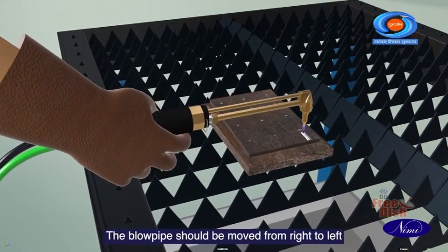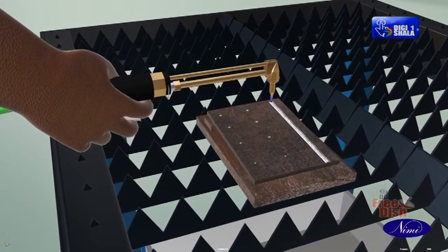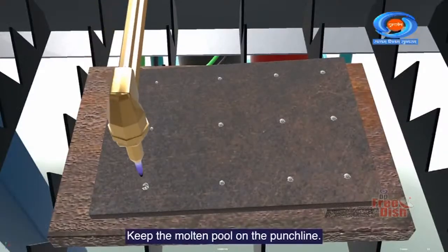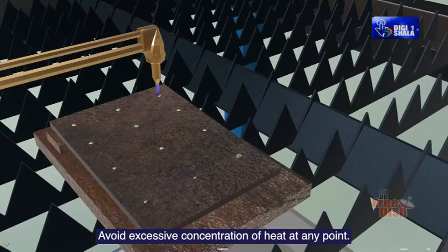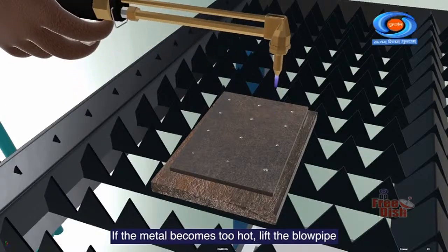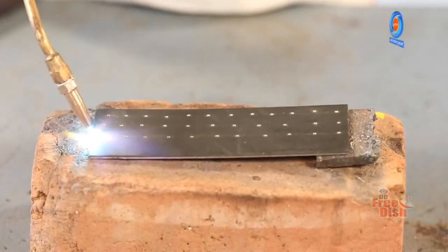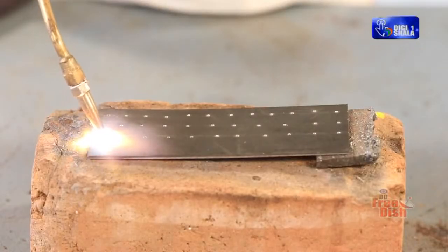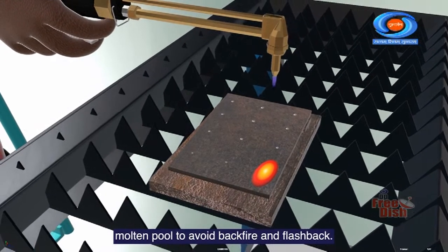The blowpipe should be moved from right to left while keeping a constant speed and a blowpipe angle. Keep the molten pool on the punch line. Avoid excessive concentration of heat at any point. If the metal becomes too hot, lift the blowpipe momentarily away from the molten pool. Do not touch the inner cone with the molten pool to avoid backfire and flashback.